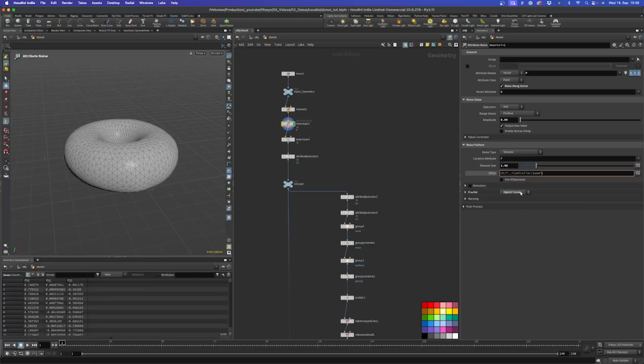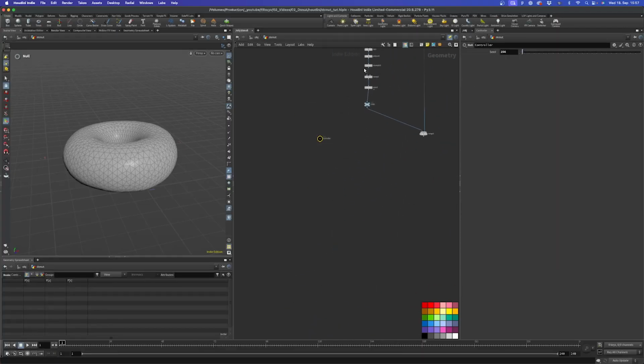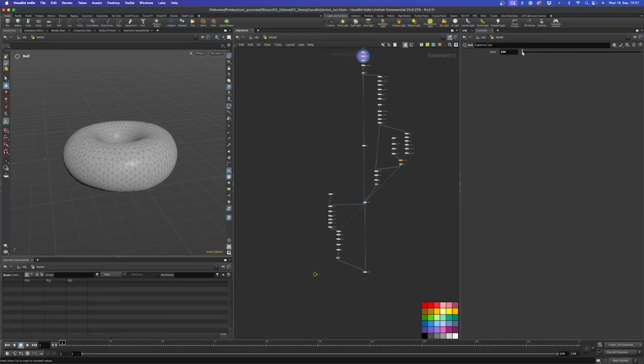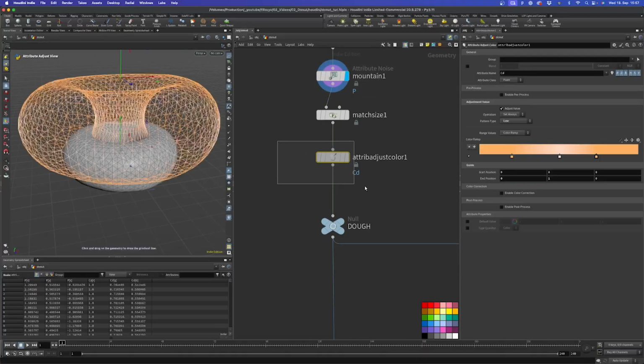And what you can see now here, Houdini puts in the path to our control null and to the seed slider. And if I click it again, you see the same number that we have inside here is now referenced up here. And what this allows us is whatever we put in here, our base shape of the donut will be adjusted accordingly. Okay, that's our first step.